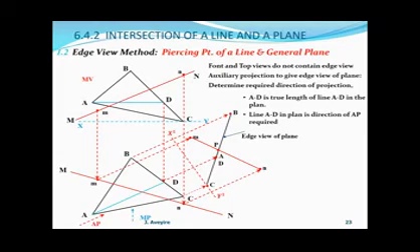So therefore, from the point V, we project backward onto the line, and that will be P, the point P on the top view. Then we take this point and project it to the top view vertically, and that will be the point P on the line over there. So we have our front view P point showing, and we have the top view P point showing.